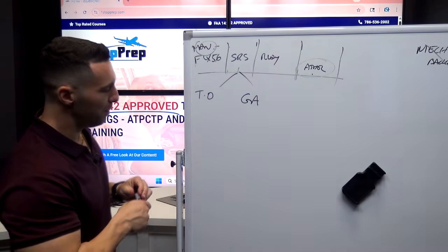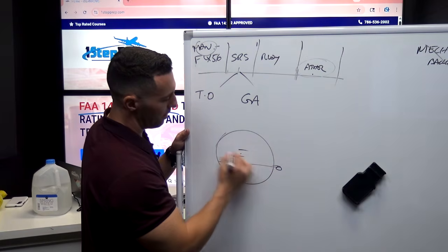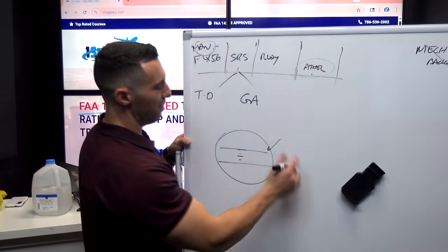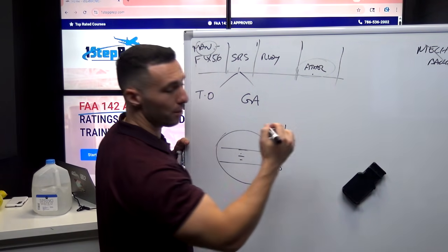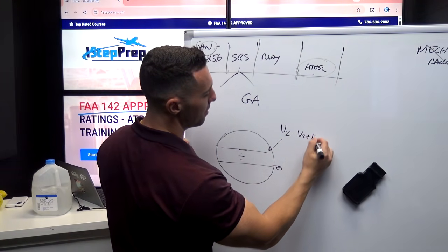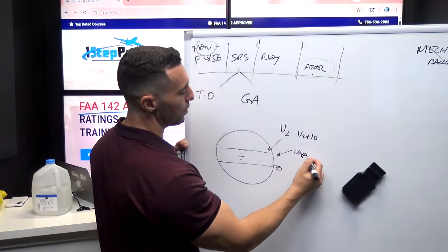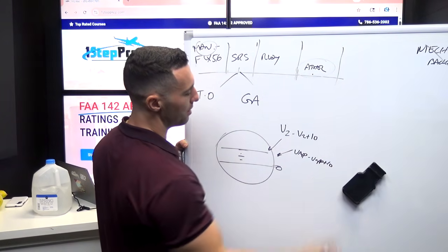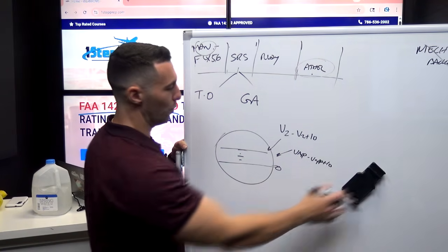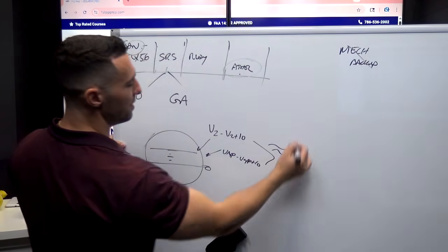Now, speed reference system basically means that the flight director bar is going to command an appropriate pitch attitude that would give me, depending on if you're on takeoff or go around, V2 to V2 plus 10 on takeoff, or VAPP to VAPP plus 10 for a go around. Translation, 15 degrees nose up, roughly. I'm going to say that with a big roughly.